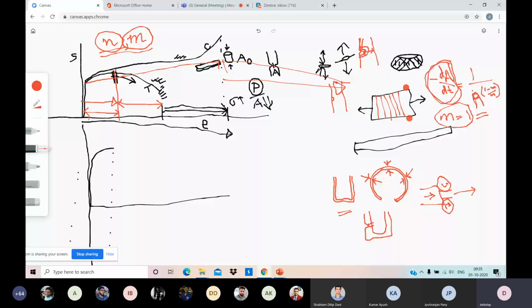Because suppose inside a body, some defects are generated. Suppose a necking has happened. High post-uniform elongation means that the material will be able to sustain that for a longer duration. Even if defects form, even if a neck forms, if it can sustain, if it doesn't break down or fail, then at least it is holding up your purpose, right? And by that, it will give you more time. By that time, you may be able to detect that a defect has formed inside.